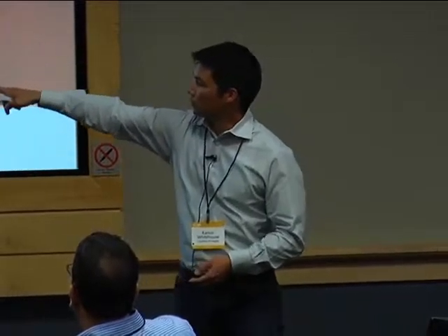But if you just take that ultrasonic rangefinder and tilt it a little bit, now you have an asymmetric sensing region, and that generates an asymmetric response. So if the person's walking this direction in the doorway, along with a cone, the shortest distance you get is right away, whereas if they walk the opposite direction, you get the shortest distance at the very end of your measurement.